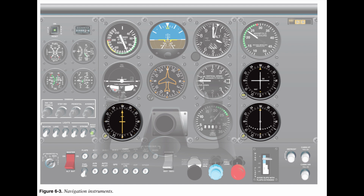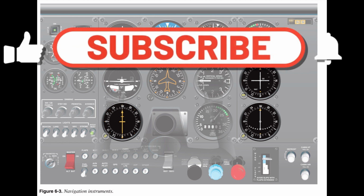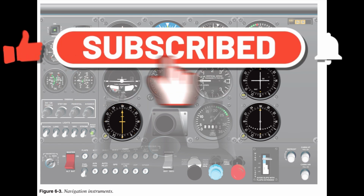3. Cross-check the performance instruments to determine if the established attitude or power setting is providing the desired performance. The cross-check involves both seeing and interpreting. If a deviation is noted, determine the magnitude and direction of adjustment required to achieve the desired performance. 4. Adjust the attitude and/or power setting on the control instruments as necessary.